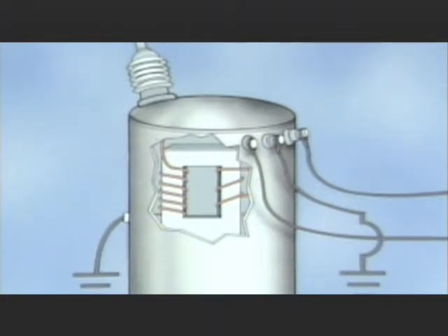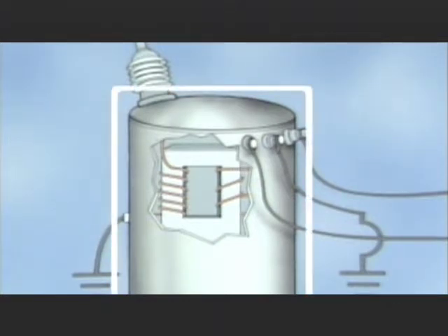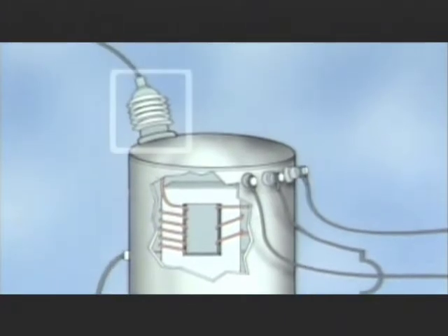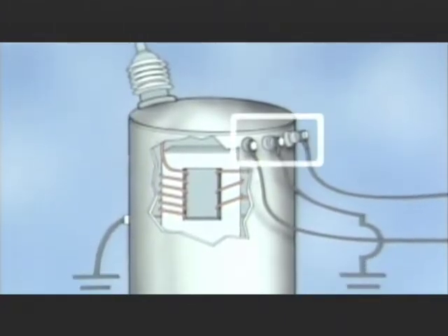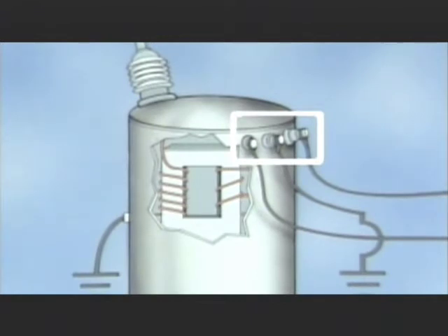You can recognize this type of transformer by the cylindrical housing, the large primary bushing on the top of the housing, and 3 secondary bushings on the side of the housing. This illustration is similar to the kinds of transformers you see on many overhead distribution systems. The primary winding in this transformer is supplied with primary distribution voltage from a distribution line on the pole.